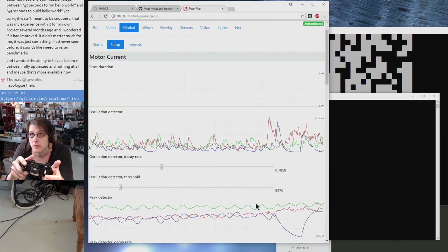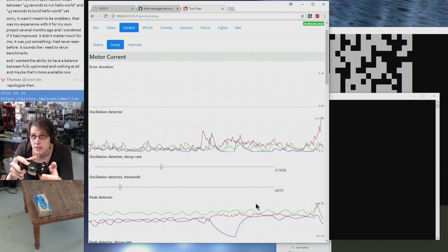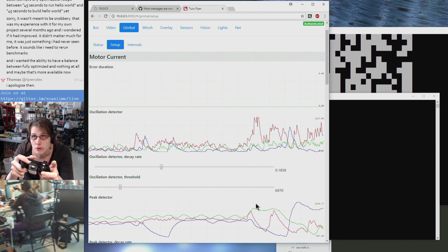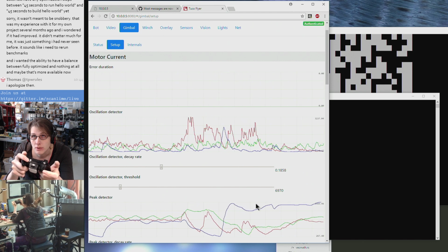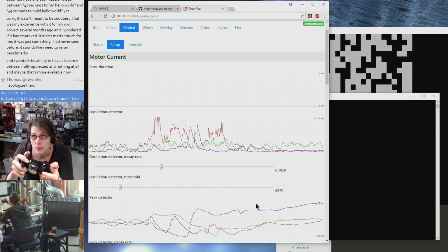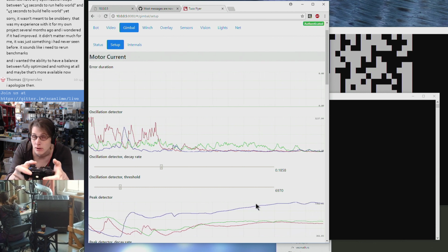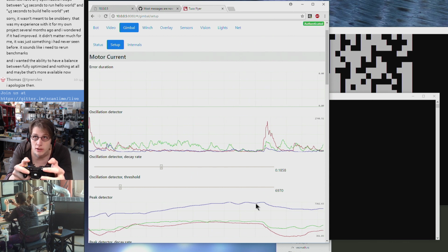And then there's this secondary and tertiary problem where the oscillation causes this oscillation detector to trip. And then that spends actually, I think, too long in the lockout mode. And then the combination of moving the gimbal without resetting the computer vision tracking rectangle causes the computer vision to try to move the gimbal back to where it was, and then the two loops fight each other. So there are probably 2 or 3 separate bugs in there to take care of.